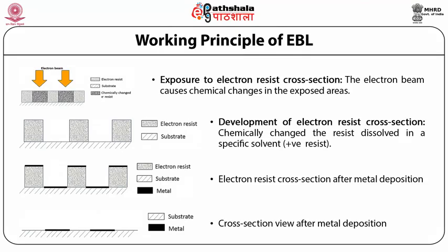An example of gold metallization using resist coating and E-beam lithography is sketched in figures 2 to 6. Polymethyl methacrylate, abbreviated as PMMA, a positive E-beam resist with chlorobenzene or anisole as casting solvent, is spin coated on the substrate.